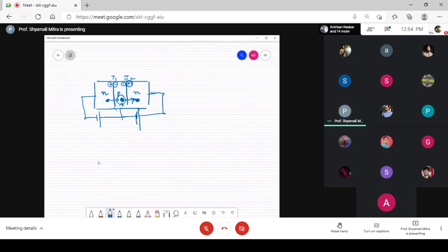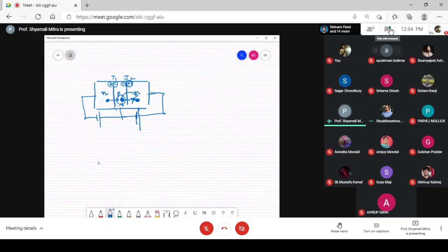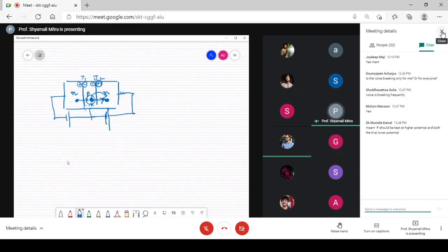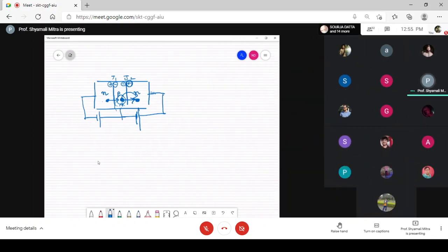So because this is the region, ma'am, if we had forward biased J2 also, then could the minority carrier not go to that side? Your intuition says it would get stuck in the P region? Okay, the P region. Look at one thing: if an electron has to move from this side to this side, what polarity in this region should facilitate this process? Obviously positive polarity, to get collected at this region. Yes, ma'am. So if you put a forward bias over here, that means the inside is connected to the most negative terminal, that must not facilitate this process. Okay. Yes, ma'am.